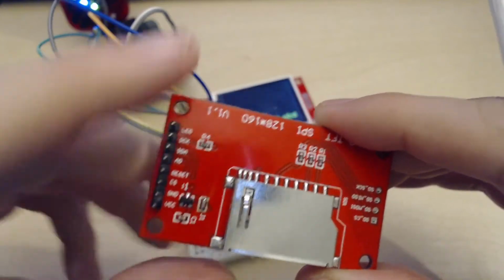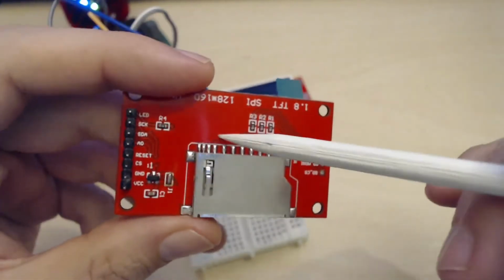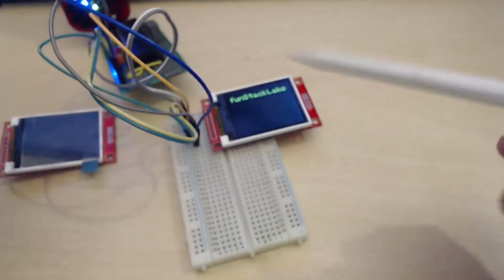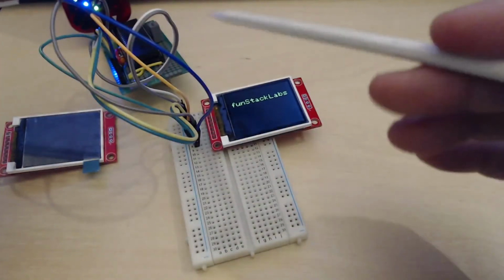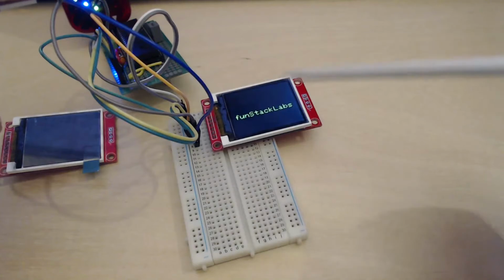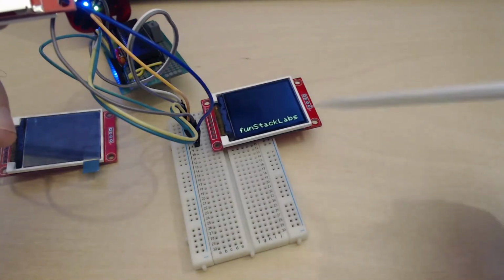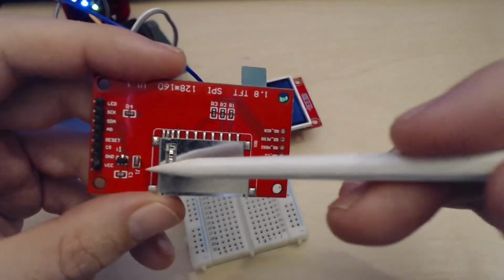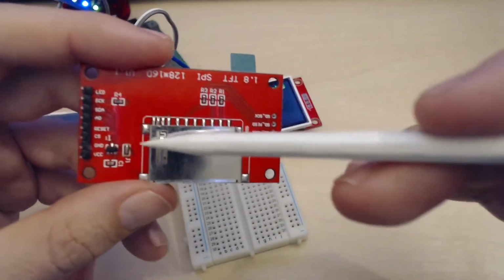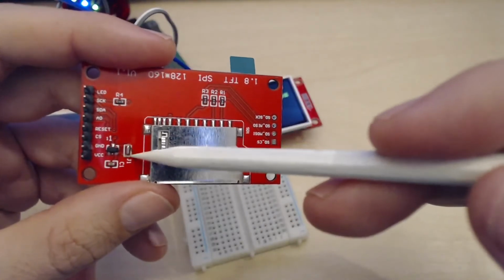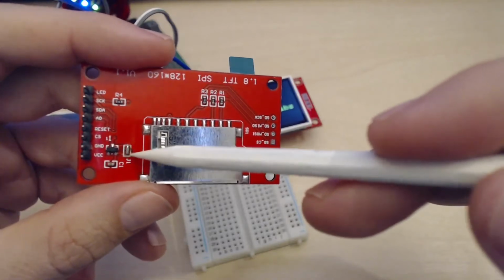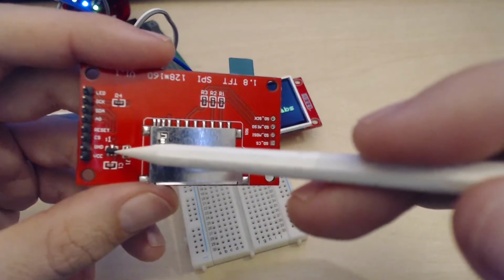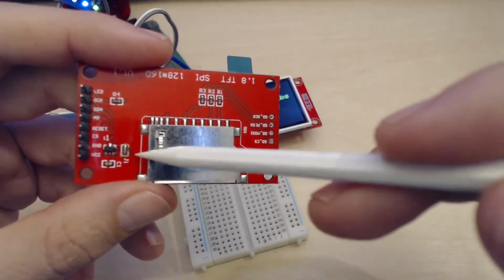the power supply. So for this one, I recommend you use a 3.3 volt power supply. It makes everything easier. The circuit here, and the driver has nothing to do with it, but the circuit we will talk about here is using a 3.3 volt power supply, and it makes everything easy. And when you use a 3.3 volt power supply, it's usually a good idea to just solder this jumper here. That shorts the internal 3.3 volt regulator. So if you don't short it, that's not a big deal.